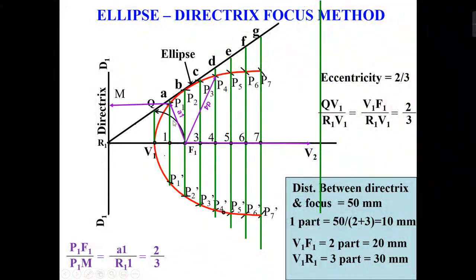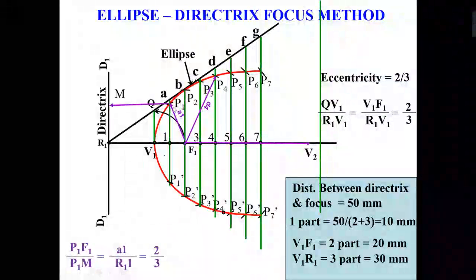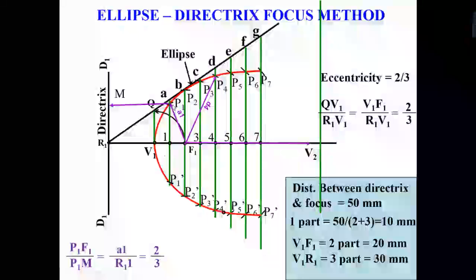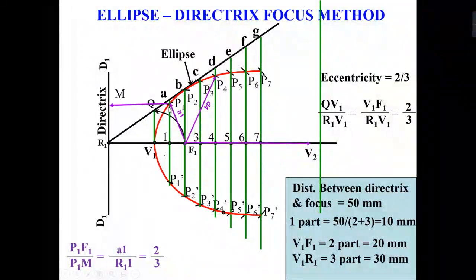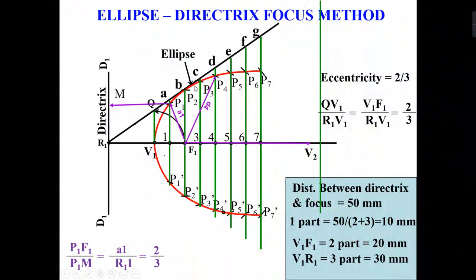And after that, when you are joining the other points, you should take some portion that you have already marked. Means if you take 3 points up to here, then for drawing the other parts you should start from here. So P1, P2 should be on the French curve, and then you can mark the other points.